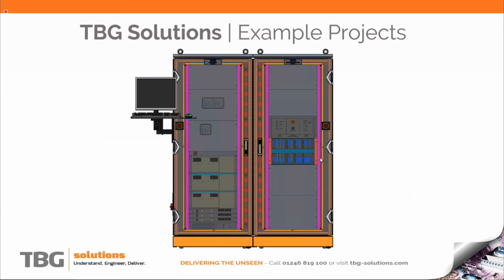And then lastly, an example of a traditional rack build that we would do. This is for testing 3 avionics PCBs in parallel. So there's a large 18-slot PXI chassis in there with some Pickering switching and things like that. And again, box instruments, PSUs, AC and DC loads, switch cards, switch chassis, amplifiers, all under a hardware abstraction layer. And it's the core of what we do, really. The more I've thought about it, the more it is at the core of pretty much everything we do.